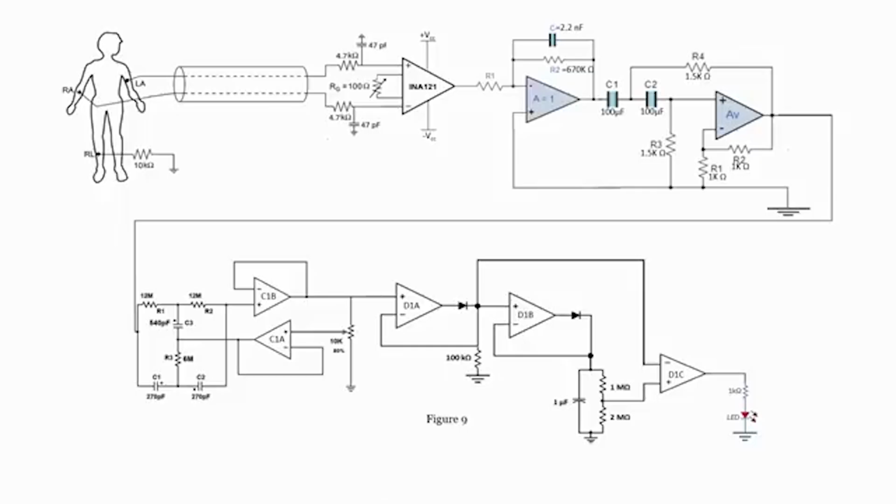Now, since we have designed the amplifier, low pass filter, high pass filter, notch filter, then a peak detector, and a trigger circuit, if we combine all of these along with the electrodes, how will the circuit look? If you see this slide, you can realize that we have a complete electronic conditioning circuit for measuring and processing ECG signals and finally measuring the BPM.